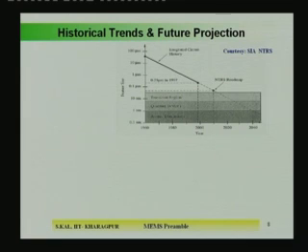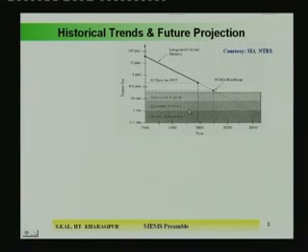Now, here is another diagram, where you can see the feature size going down. If you look into the integrated circuit history, below 0.1 micrometer is the 10 nanometer range. This is one transition, 0.1 micrometer to 10 nanometer, and then another transition level is 10 nanometer to 1 nanometer. This transition is very important, because these are basically the quantum devices. The lattice constant of silicon is nearly 3 or 4 or 5 nanometer. If you go to 10 nanometer, that means just 2 or 3 atomic diameters, a few monolayers of silicon within which you have to make the devices. There the normal physics of the transistor may not be valid, and you have to go into quantum mechanical analysis. Those are basically the quantum devices.